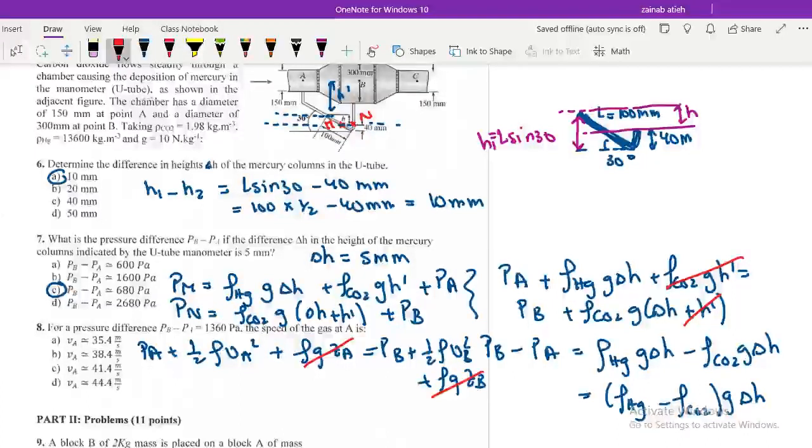بدي أنا كمان ال PA minus PB it's given. بيبقى معي بدي أجيب أنا ال VA so أنا بدي أخلص من ال VB. كيف بخلص من ال VB؟ بحاول أعمل relation بستفيد من ال continuity equation. I will write things not in details because you must have the answers. Okay and there's not enough space so I have to write in short. So using continuity equation معي أنا الاريا على A times VA بتساوي الاريا على ال B times VB.